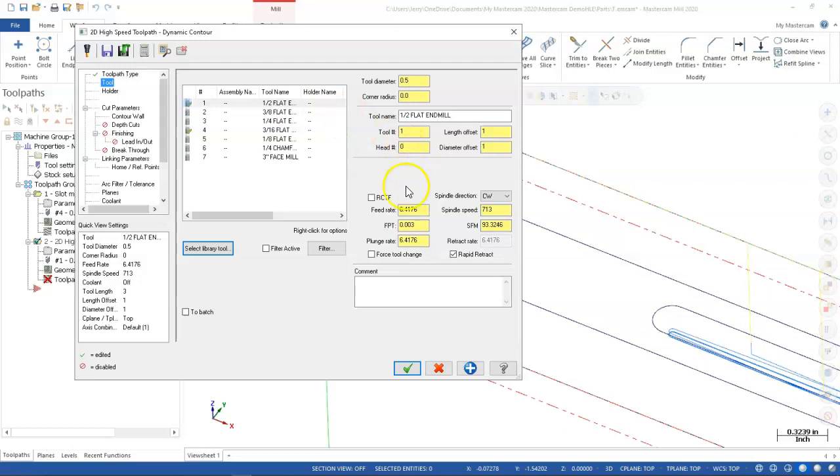The tool, we already picked the 1/2-inch. Let's see what it looks like at 300 surface feet. That one could probably go up to as much as 3,200, but since we ran the other one at 300 surface feet, we'll stay consistent. And the feed per tooth can go to, let's go down to 1,000th. Well, I want to go a little bit further than that. Let's just bump it up to 8 and see what we get. All right, so again, some of these are just going to be take your best guess and then observe and react to what you get at the machine.